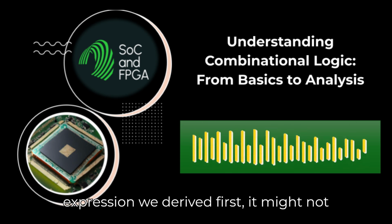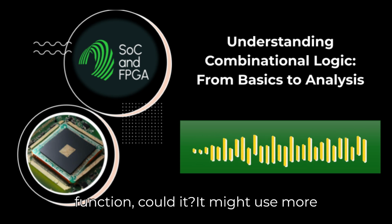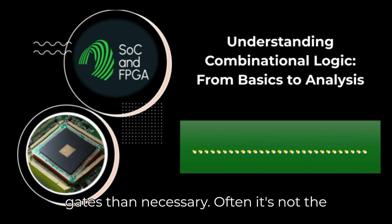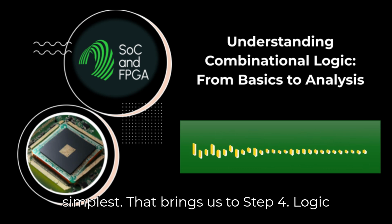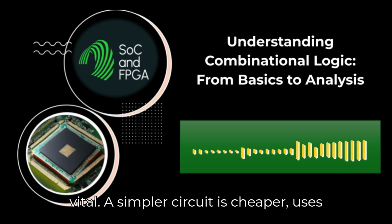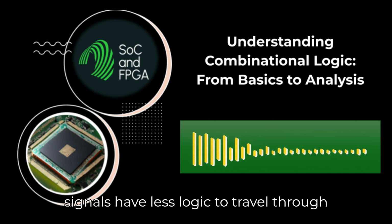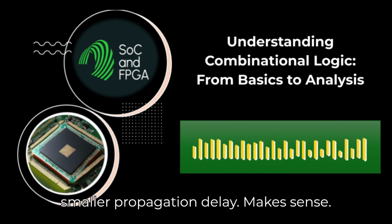Now, that expression we derived first, it might not be the simplest way to represent that function, could it? It might use more gates than necessary. Often it's not the simplest. That brings us to step 4, logic simplification and optimization. This is vital. A simpler circuit is cheaper, uses less power, and is usually faster because signals have less logic to travel through, smaller propagation delay. Makes sense.